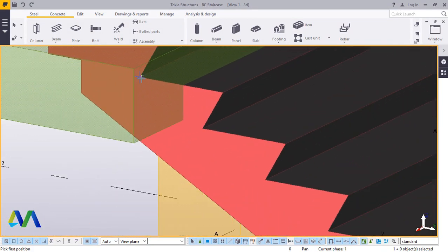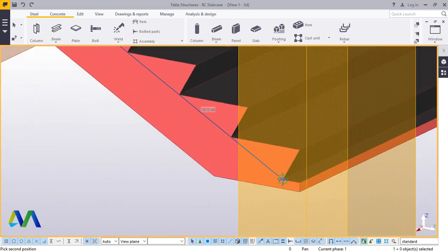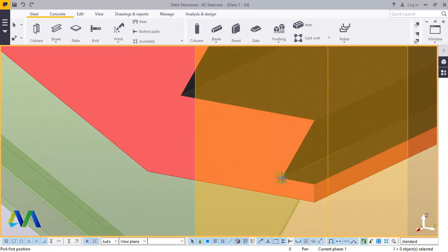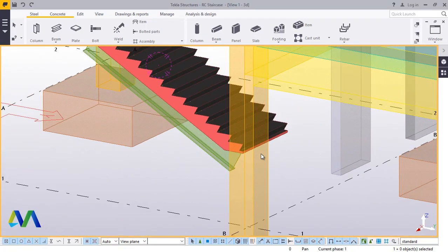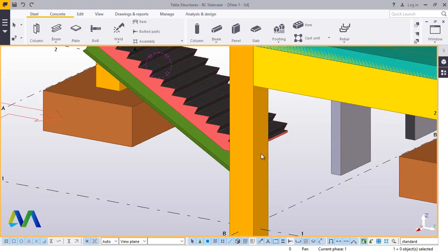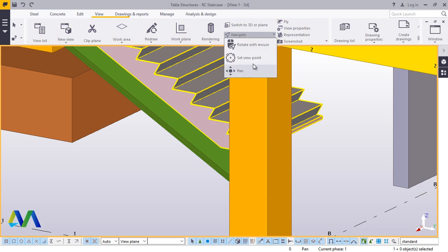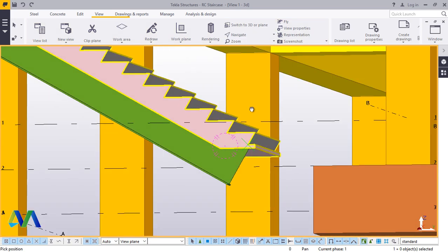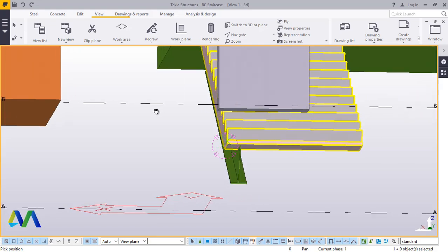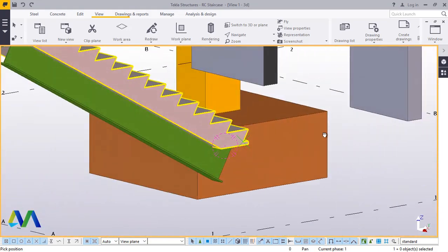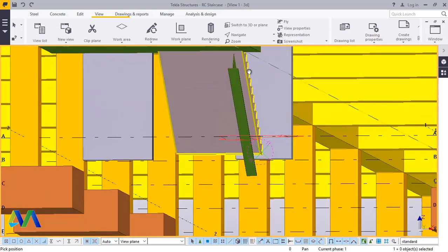We'll click from that end and run all the way to the bottom end here, and click there. If you press Ctrl 4, you'll be able to check the position of the beam you've just placed. Click that and turn this round. Is exactly in the middle.